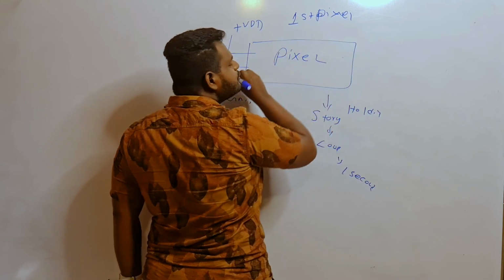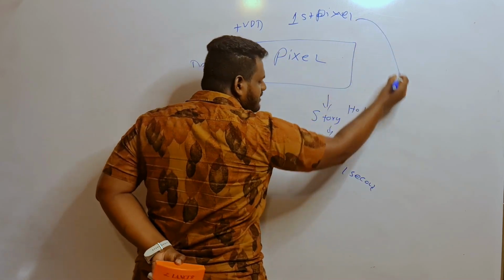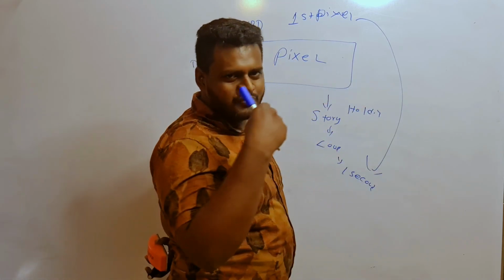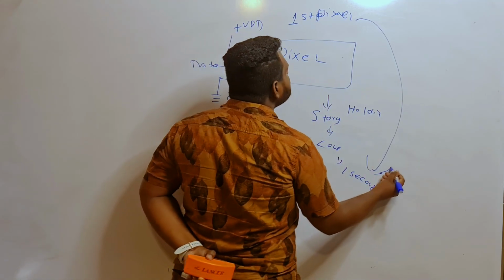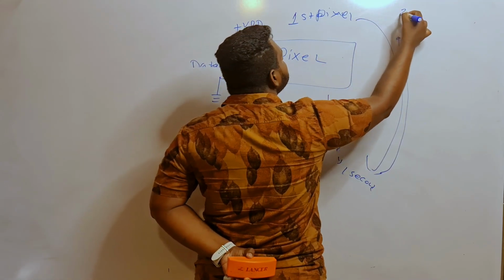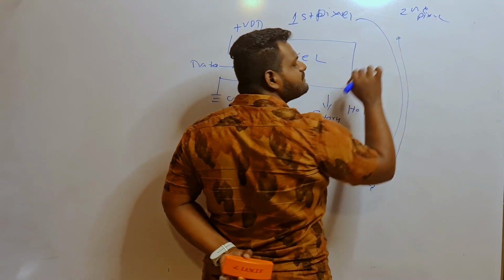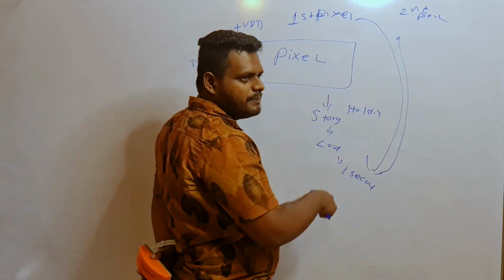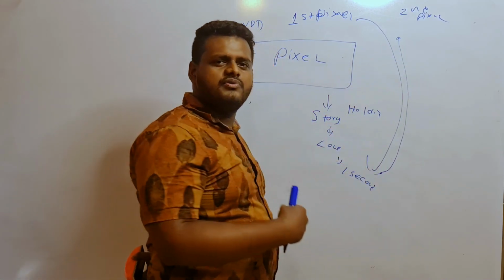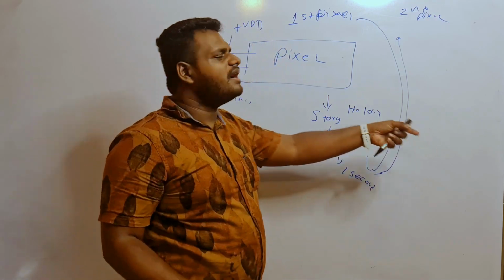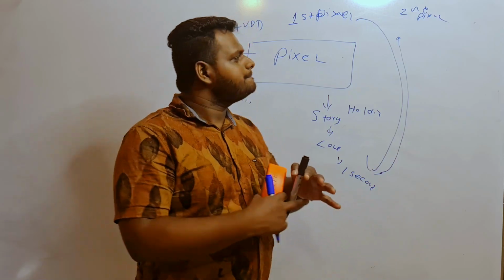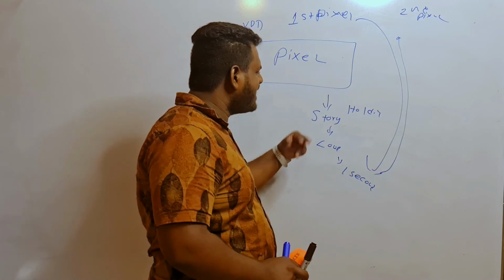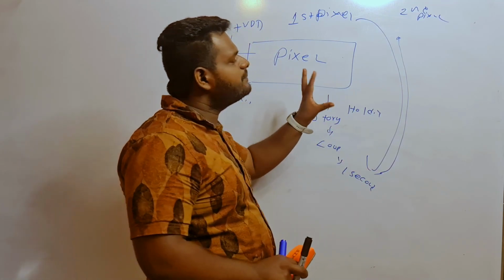Just write the first pixel, put the data line there and come back here. If you want to run a loop or any other calculation, evaluate that, then come back and write the second pixel data again with that timing diagram, logic 0 and logic 1 according to the Neo Pixels. Then again, if you want, you use a loop or something, then put the data line to some state. Then you can think about holding time and do it yourself. Likewise, a simple mechanism goes on behind this Neo Pixel.